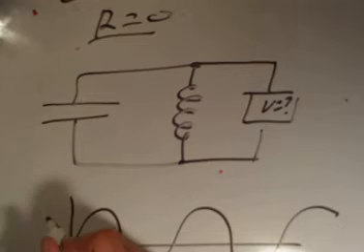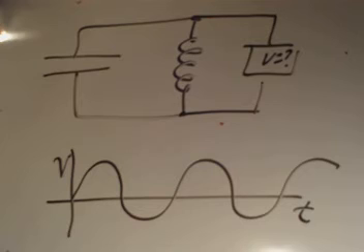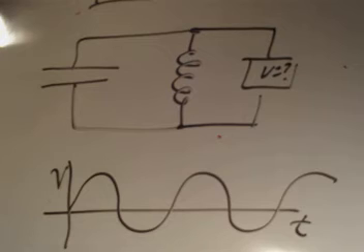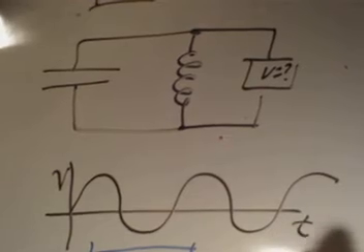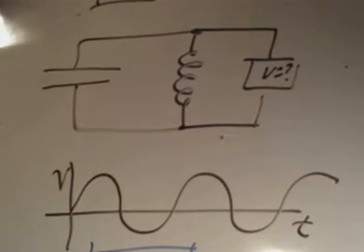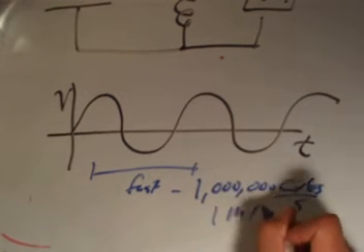So this is voltage here, this is time here, and you created an oscillation in this voltage. This has very huge concepts for us, because you can choose values of these resistors and capacitors so that this oscillation can be comparatively fast. And by fast I mean maybe 1 million cycles per second. So this is nothing like the 2,000 hertz sound wave that you did before. This is like a megahertz, 1 megahertz or something like that.